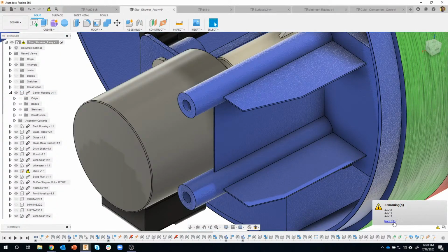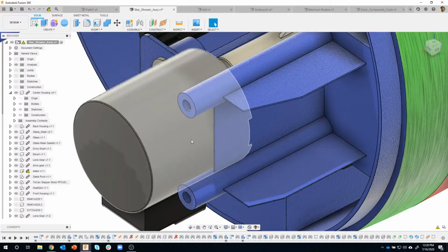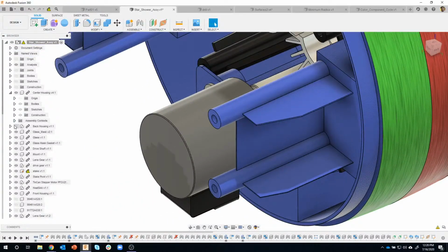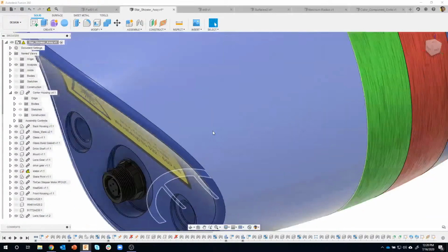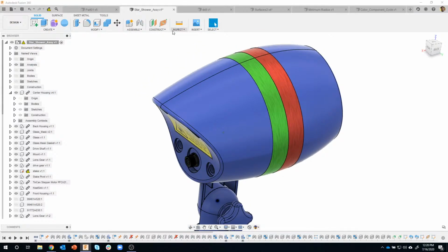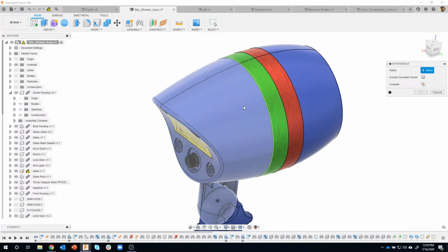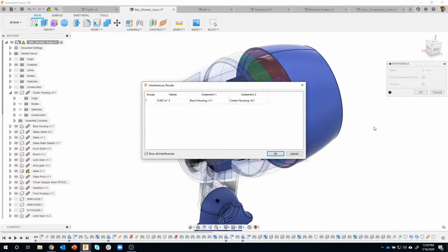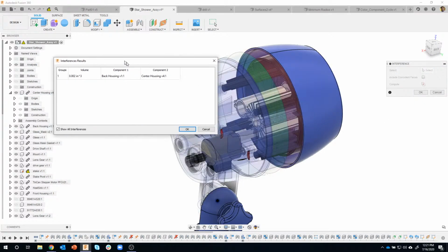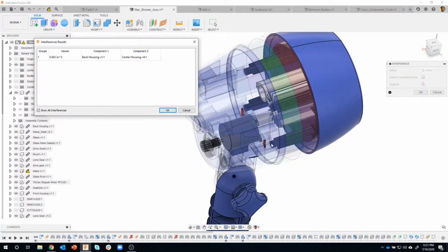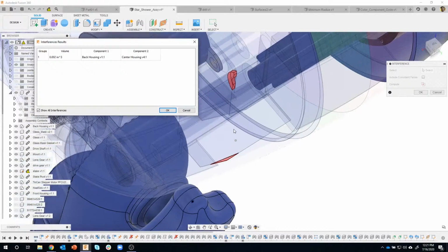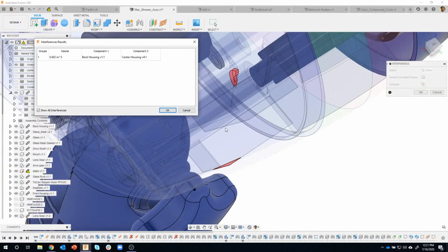So you can see how it's computing that. A couple of the axes didn't compute, but that's okay. And then let's turn the back housing back on. And I'll inspect one more time. Instead of doing the whole thing, I'm just going to pick the 2 parts that I'm concerned about. So you'll notice instead of 31 selected, it only says 2 selected. And I'll clash.